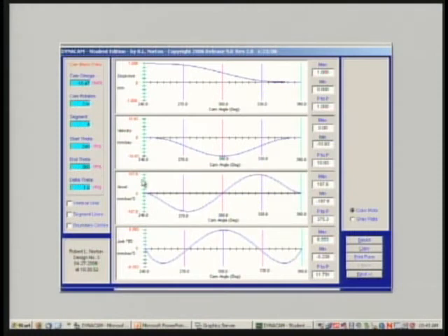The flattening increases with each integration. Notice how flat it is at the beginning of the displacement. Virtually nothing is happening over the first 10% of the time here, which means I could actually have increased my time, that is, increased my beta, which would reduce all of the peak values here, and still had the smoothness of the continuous jerk function, but perhaps, not perhaps, I would have some reduced values of acceleration at the peak. That's getting a little bit beyond where I want to go with this introduction, but let's continue.